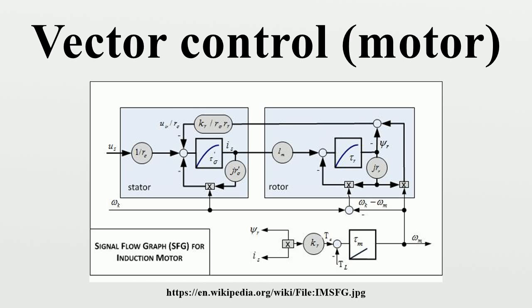Decoupled torque and field currents can thus be derived from raw stator current inputs for control algorithm development, whereas magnetic field and torque components in DC motors can be operated relatively simply by separately controlling the respective field and armature currents. Economical control of AC motors in variable speed applications has required development of microprocessor-based controls, with all AC drives now using powerful DSP technology.